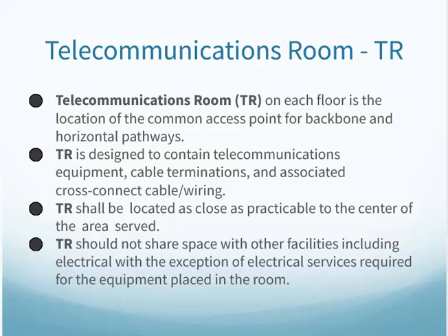And again, remind us about some things in the telecommunication room. There should be at least one on each floor. If you have a multi-floor building, there should be one on each floor to service that floor. It's going to house your patch panels and your switches, those types of things. It should be located to the center of that area as best as possible. That way you're limiting distances. And it should not be shared with really any other facilities. There shouldn't be lots of electrical panels and other things in there, pumps and whatever. It should be kind of a dedicated space to this as best as possible.